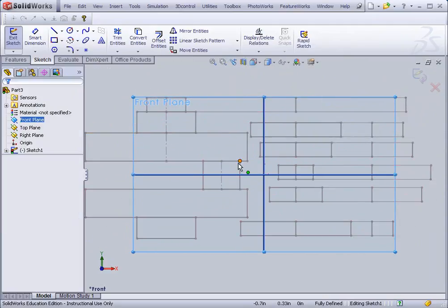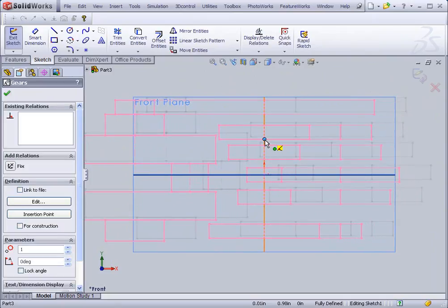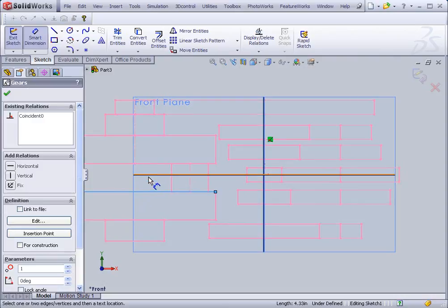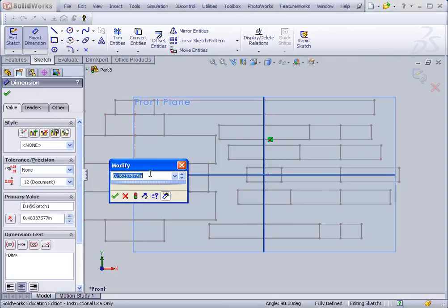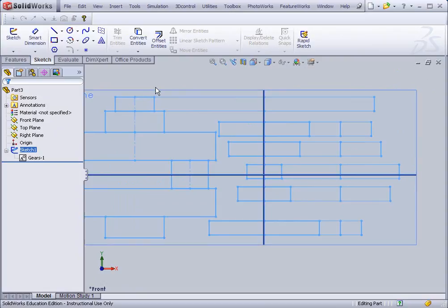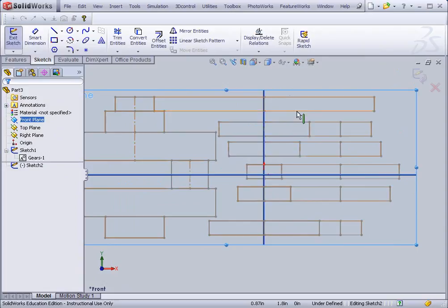Last time, if you recall, I lined up the center of the crankshaft with the XY axis. This time I'm going to line up the center of the driven shaft of the transmission. And then here I need my 10mm offset. Check OK. Now, I'm going to click on the front plane and open a new sketch. So remember, 2 sketches here, because I'm pulling all this geometry right out of the layout block. And then I'm going to start converting entities.